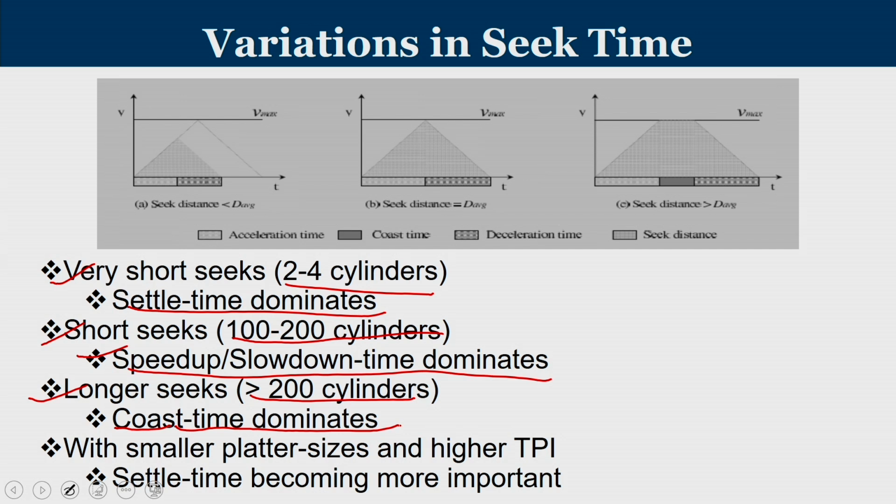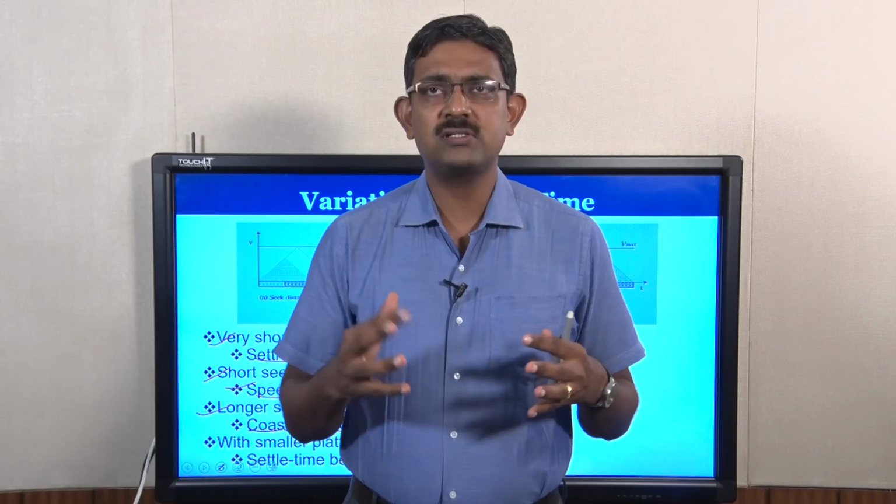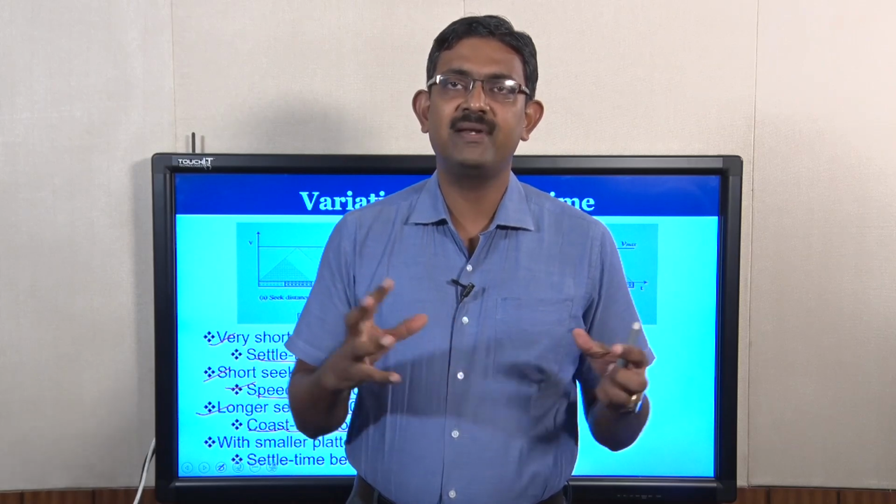With smaller platter sizes and higher tracks per inch, settle time becomes more important, because the tracks are closely spaced. So, in order to locate the corresponding cylinder number with high precision, your settle time will take a little bit more time. So, the whole concept of acceleration, coast and deceleration and settling can be defined as the case of an elevator.